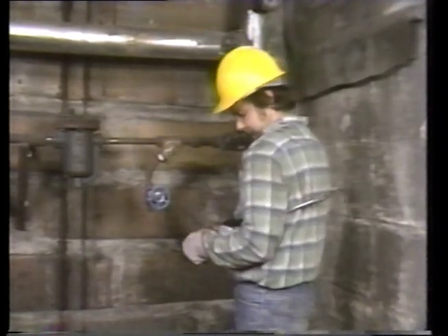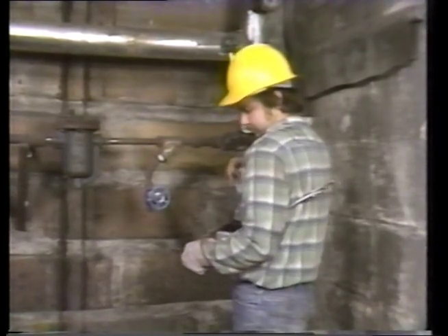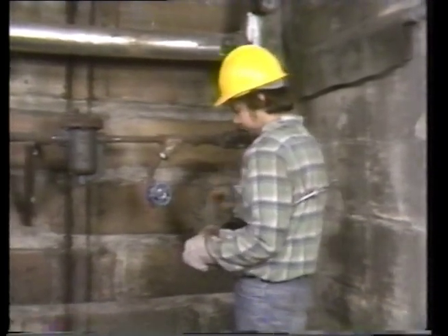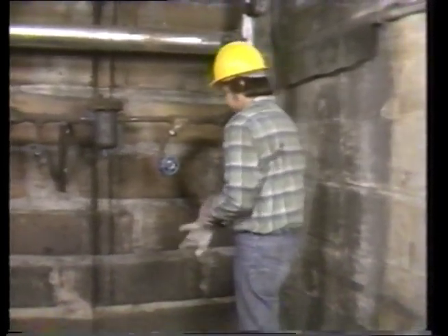When you compare it with the expected temperature, you find that it is too low. Now, what's this mean? Well, it could mean one of several things. The trap itself may have failed shut. The inlet or outlet valves may be closed, causing condensate to back up in the line, or there may be an obstruction upstream of the trap. Now, each of these possible causes should be checked out.